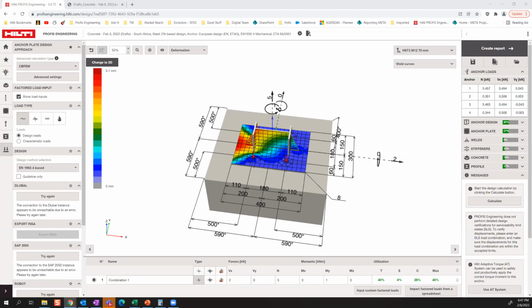Oh, okay, awesome. So to be frank, what is the answer that you want to give, Rishan? So Ahmed's question is more, would the software allow us to do a combination design under one base plate? So a few HD bolts in place, and maybe if the guys misplaced it, a couple of post-installed anchors. Okay, got it. So a mix of cast-in-place and post-installed anchors. Unfortunately, it's a no. It's practically not possible, as far as I know, to calculate it within the same software. I remember this question coming before as well, and as far as I know, there is no answer to that so far.